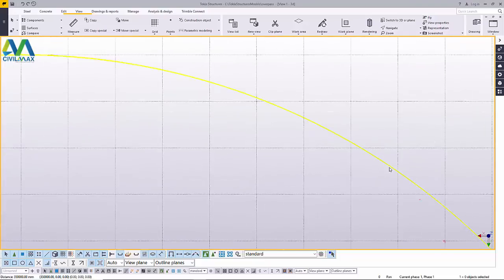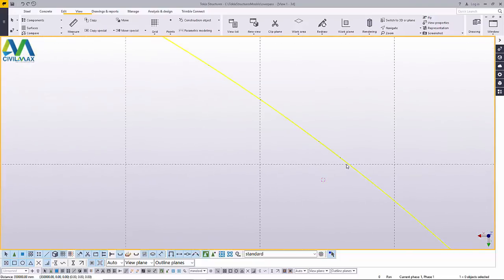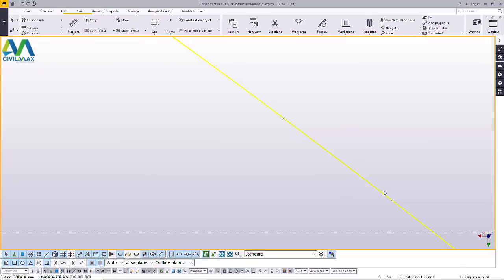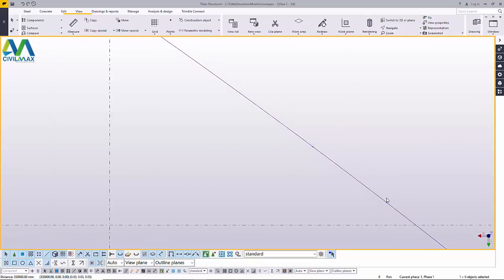Now I'll bring this close, and we will first of all create our pillar here, our concrete pillar. Remember this profile we did in AutoCAD previously, and if you've been following this channel religiously, you won't have a problem creating profiles in AutoCAD, then importing them into Tekla Structures to introduce a customized profile.